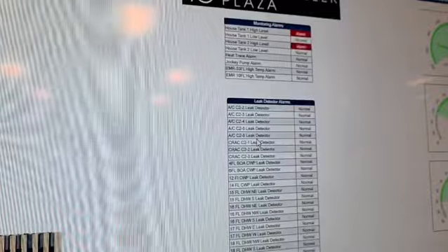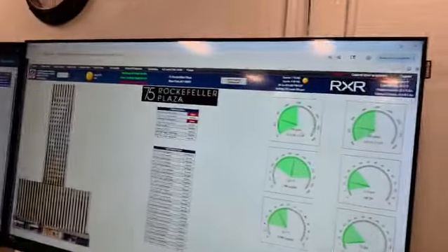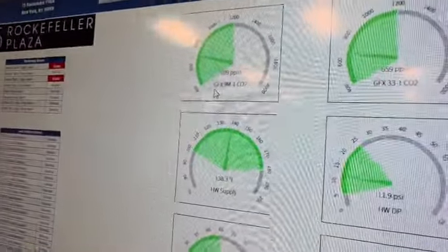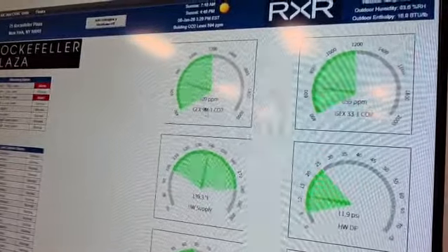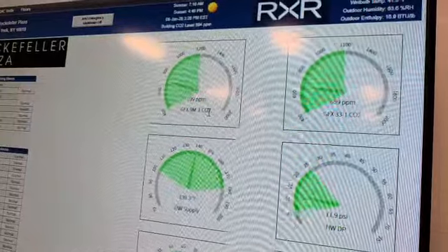I need 2-5. I know where it is. You go, right? In here, you could see it. ppm, parts per million, right? So this is GEF, general exhaust. 9M, that's the mezzanine. It's measuring CO2, right?